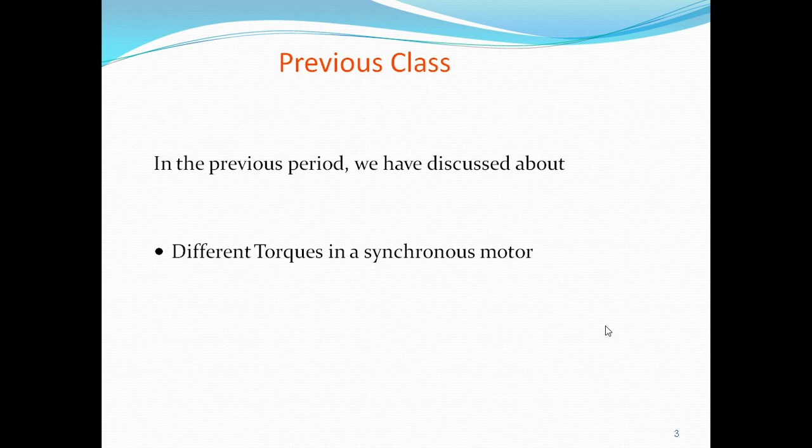If you apply the load, the motor will bear it and run at synchronous speed. If you apply more load at a particular instant, the motor is not able to bear any more load. At that time, the motor comes out of synchronism and stops. When you apply the load, the axis of the rotor and the axis of the stator will have some phase difference, called the load angle or coupling angle.